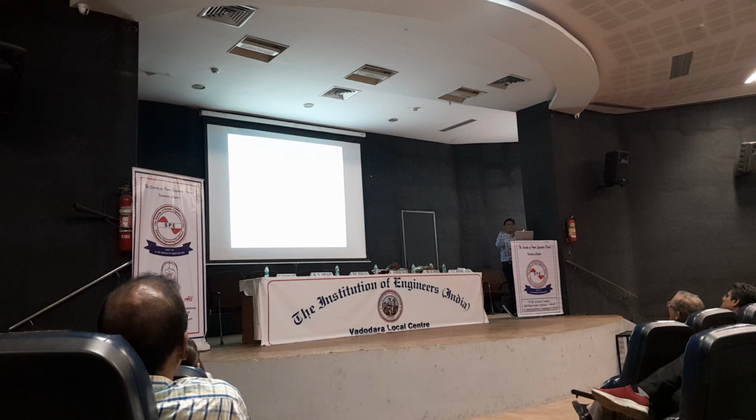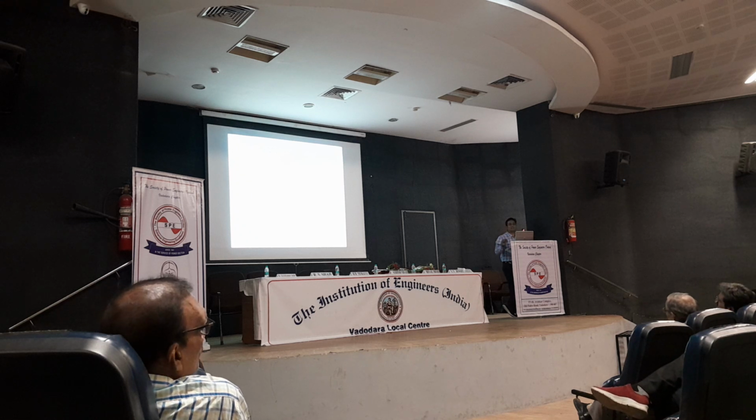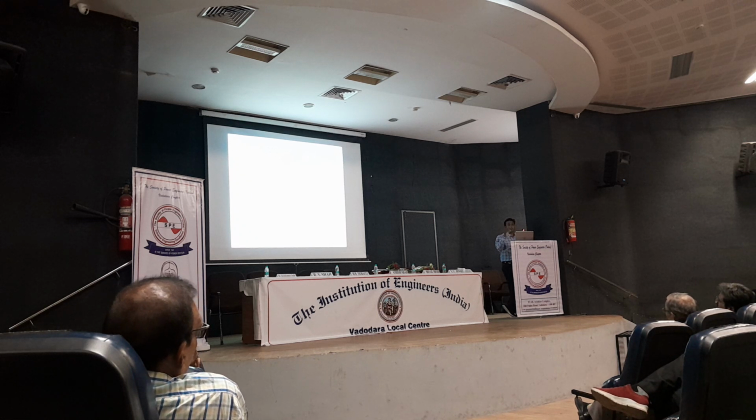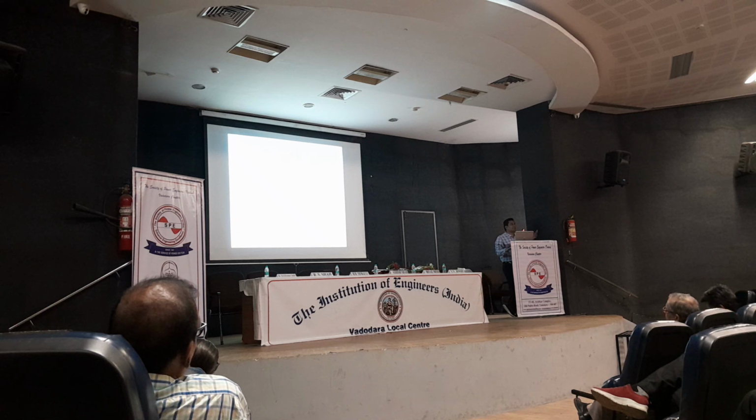And the star connection, maybe you have come across this in studies, with star neutral reactance given. That is useful for zero sequence components of current, because whenever we are doing hand calculations for balanced or unbalanced faults, we take the help of symmetrical components to do the analysis. So all the information is given, and the fault impedance value is also given. Let's say the fault impedance is 0.16 ohm.